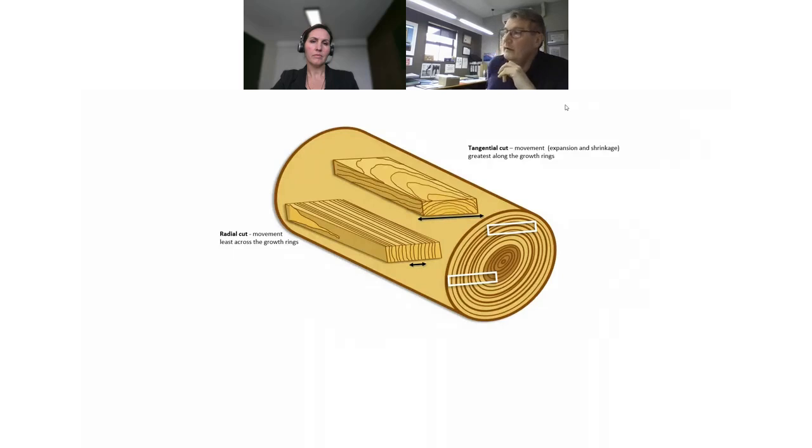All right. And contrary to popular belief, the tree's grown that way. The cells are almost set in stone, excuse the pun. They're not going to move lengthwise very much. It's not like metal, like bridges or railway tracks where they have those expansion joints and it moves that way. Timber doesn't. Timber moves widthwise. Again, when you look at the flat sawn, along the growth rings.